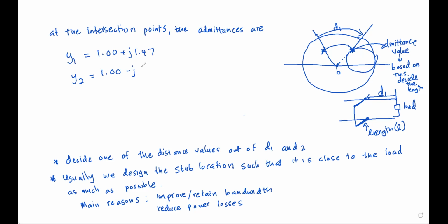What you need to do is just find the value of the admittance in here. Since we are considering the admittance in here, in this place also, you will be measuring the admittance. This place we will say y1, and the next intersecting point we will take as y2. The admittance value that you find using the Smith chart for this point will be the value that you just measure from the circles. So this entire chart you consider as an admittance chart in this whole calculation.